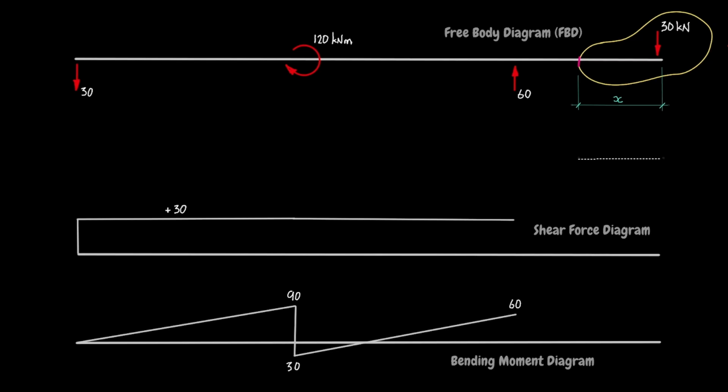Draw a free body diagram for everything inside the bubble. Note that the cut face in the free body diagram is a left-hand face. In other words, the outward normal from the face points to the left. This means that the positive directions for the internal forces is reversed compared to the previous 2 cuts, where we were dealing with right-hand faces.